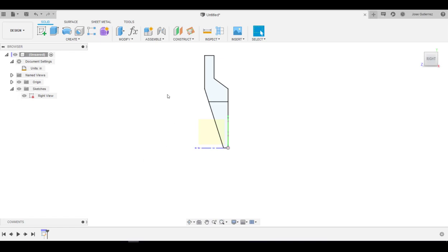Okay, so for this, I've decided to start with the right sketch. The reason is that I can get most of the complicated geometry from the right sketch. The second reason is that there are two really logical sketches you could use. With the right sketch you could extrude most of the body, and with the front face you could extrude the comb teeth, but you actually don't even need that. So I'll show you both ways.